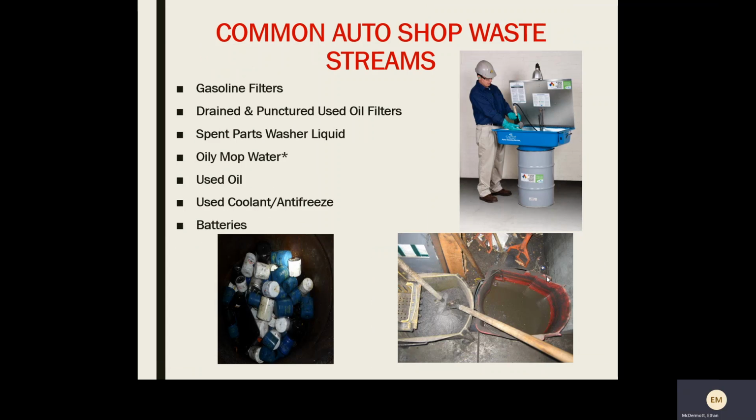Now, we're going to talk about some of the common waste streams generated by different industries. In auto shops, gas filters and used oil filters are contaminated with used oil or fuel and need to be properly managed. However, there are some relaxed requirements for these wastes that we'll cover later. Vehicle fluids like used oil and used coolant are common hazardous waste streams. Spent parts washer liquid and oily mop water can also be hazardous. And lastly, lead acid batteries contain lead and sulfuric acid. However, these wastes also have some relaxed requirements that we'll cover towards the end of the presentation.